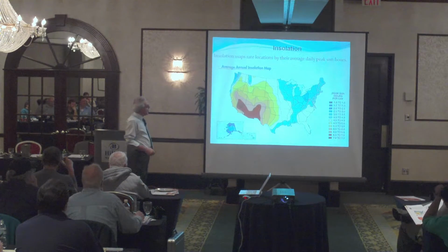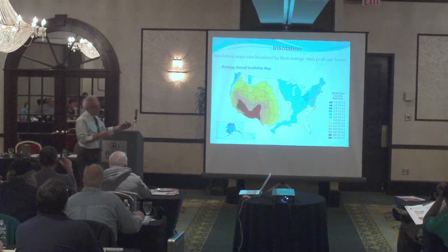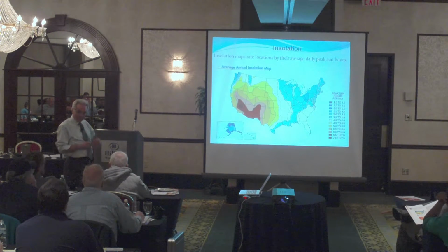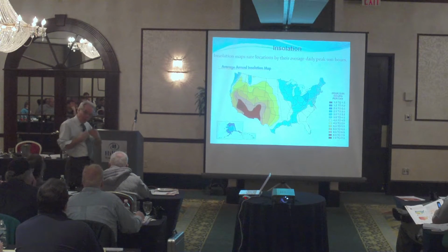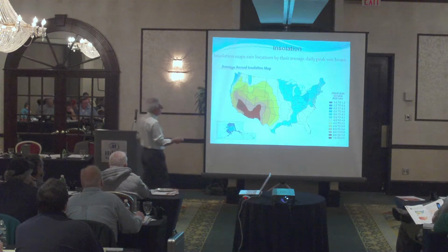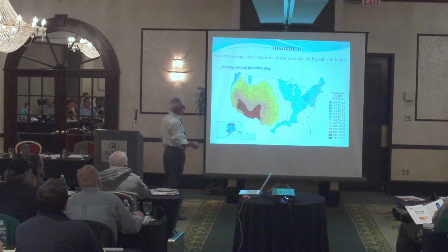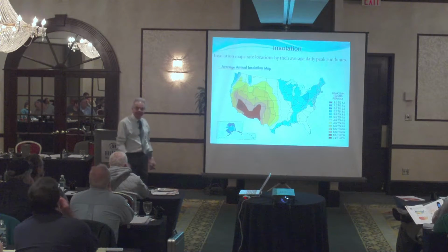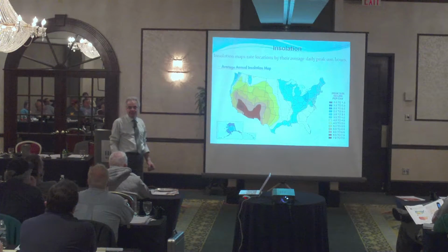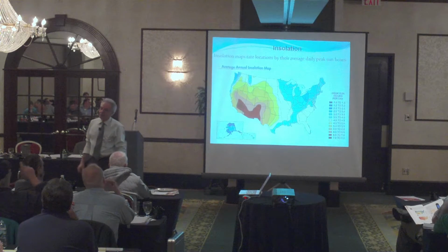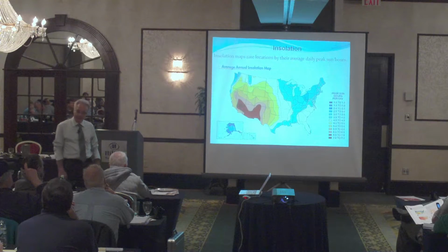Is that clear? Now, this data has been tabulated with all the parameters available to you. So if you take a certain town location, you can pretty much find out exactly the amount of sun hours. Okay, that's peak sun hours at a certain angle, right?